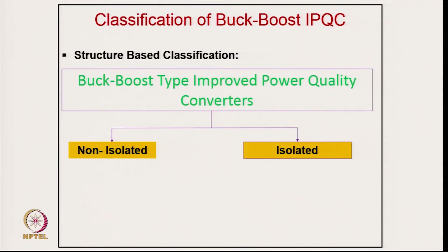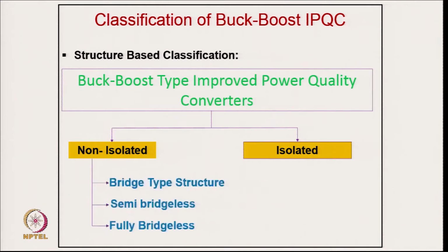In many applications, we use non isolated topology, which requires a DC supply, maybe constant or variable DC supply, and of course, for isolated configuration there are plenty of applications, because all these electronic gadgets which we are talking about, some of them need an isolated supply. For providing isolation we have the high frequency transformer, whose size, cost and weight are also reduced, and efficiency also increases.